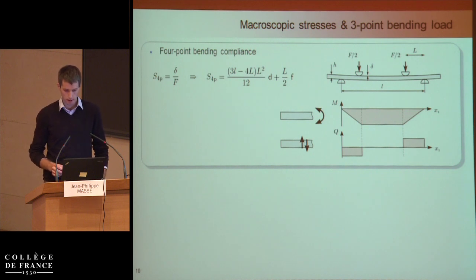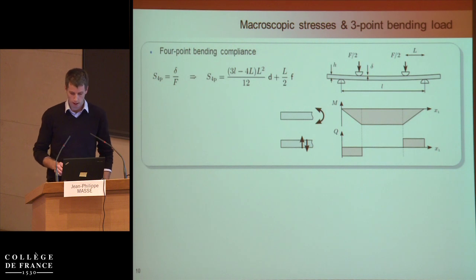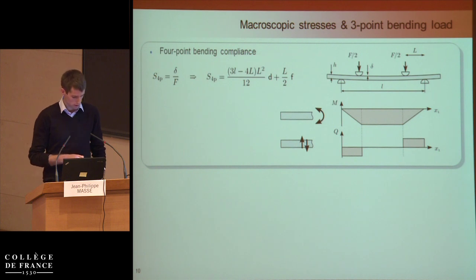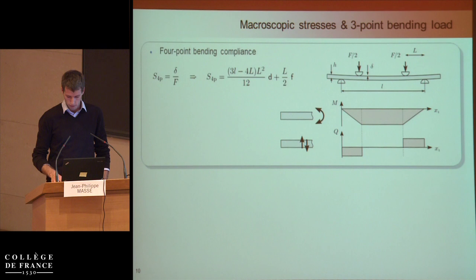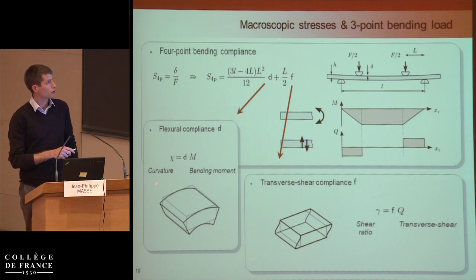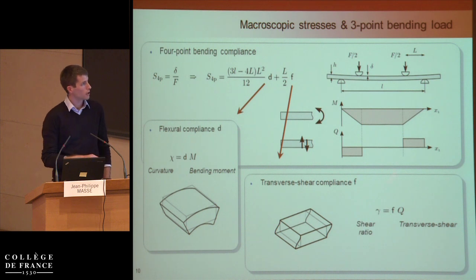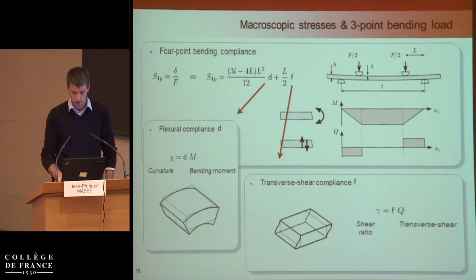And so, still looking at the 4-point bending test, the compliance has two contributions. The contribution of bending, that one, and these terms for shear. The bending compliance links the curvature with the bending moment, and the transverse shear compliance links the shear ratio with the transverse shear.